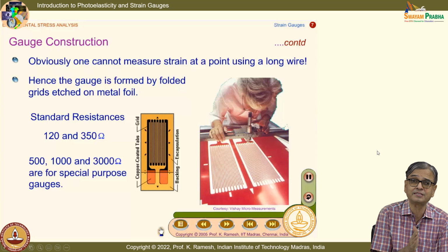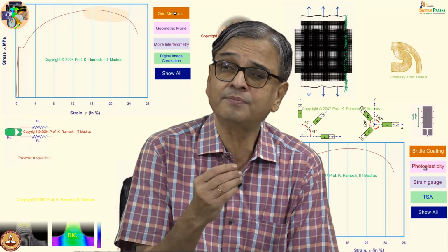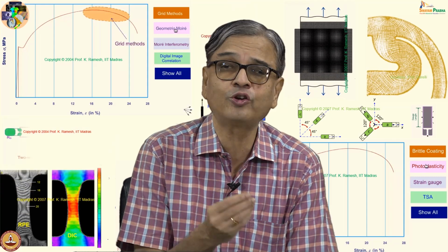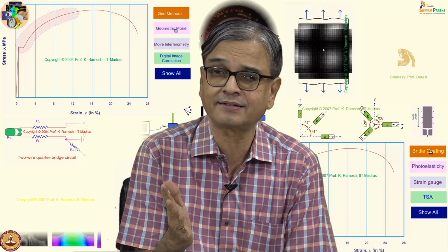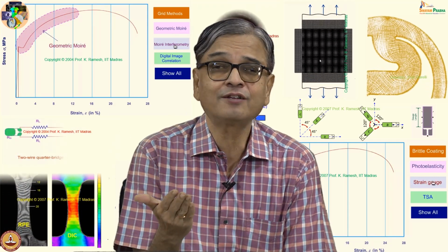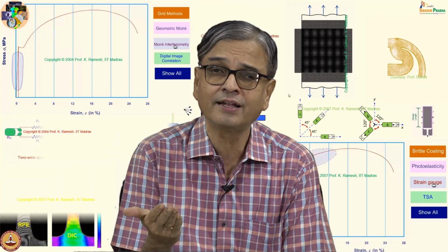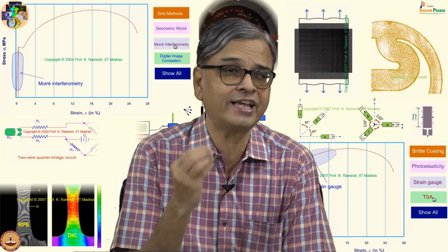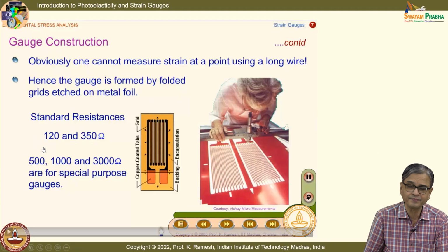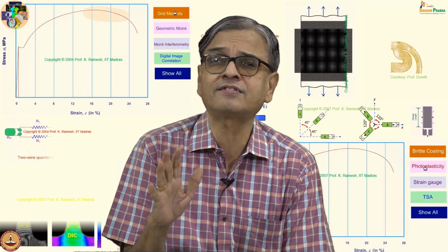Please write down these numbers. Numbers are very important. In engineering, certain numbers need appreciation. When I say calibration constant, what I am looking for should be close to 2. Never forget that. And when you look at a basic strain gauge, we said that even if I want 100 ohms, I need a long wire, and the least resistance available in a standard strain gauge is 120 ohms, and it is a technologically influenced technique.